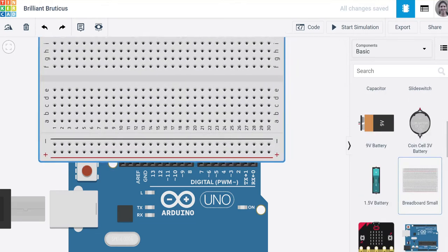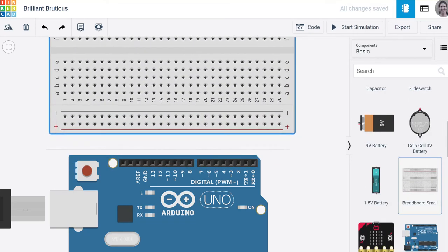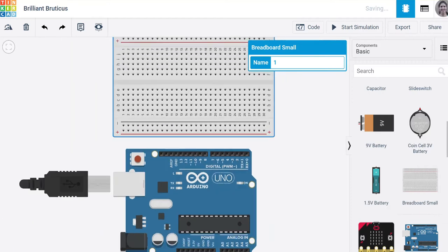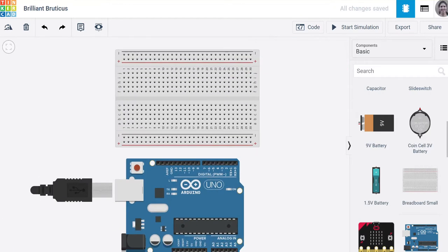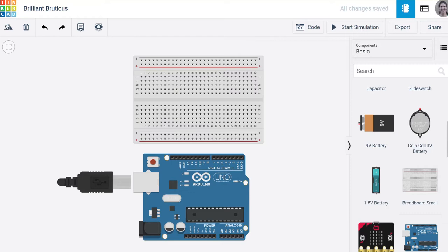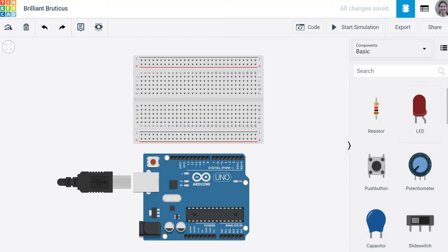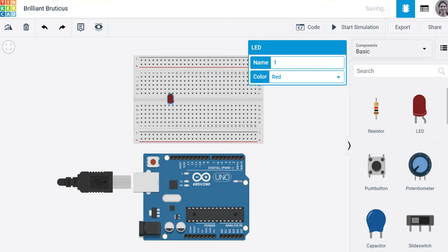So we take the breadboard and we'll put it on top of the Arduino. That will be really useful. That will remove some wires. Okay. And we want to have 3 LEDs. So scroll up. Let's add a red LED anywhere you want in the row E.